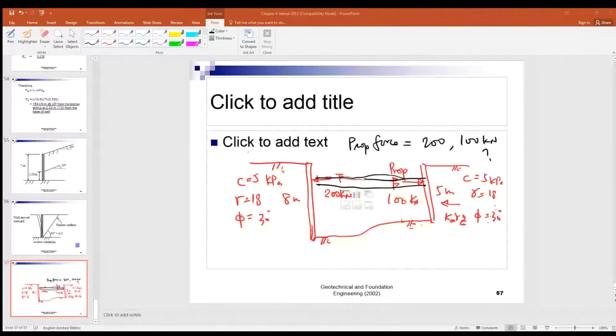For this part will be discharged by this channel, right? And for the upper part or individual part will be discharged by the channel here, right? So we divide the slope surface into several parts, right? Instead of one. So that will facilitate the drainage of any rainwater falling on the slope surface.